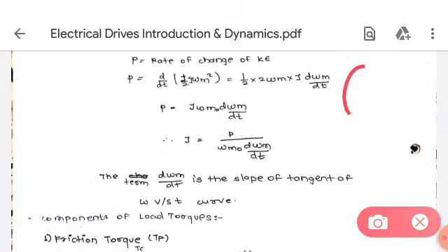Flywheel is just a disk, heavy disk, metal disk coupled to the motor, and this disk is having a radius. So in case of disk, it is a radius of gyration, rho. So whatever is the radius of the disk, it is a radius of gyration. Otherwise, if it is somewhat like some different surface and rotating, then we have to calculate the radius of gyration by calculating some mean value or like that.